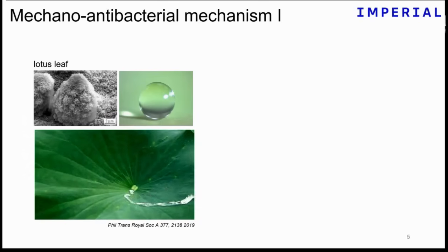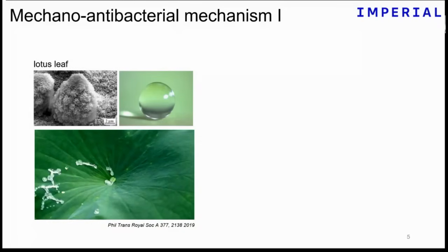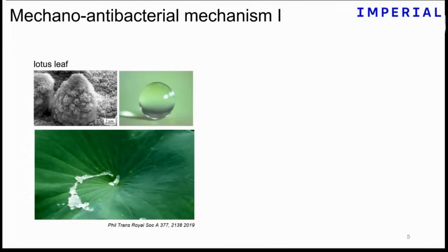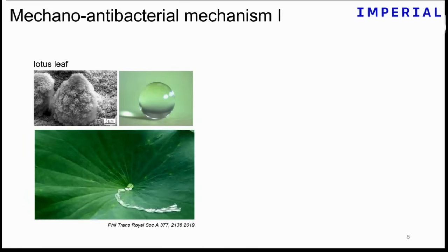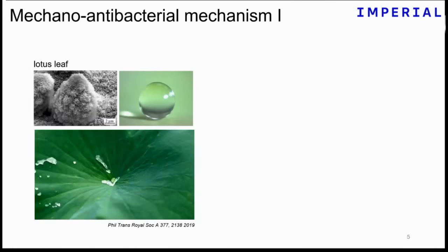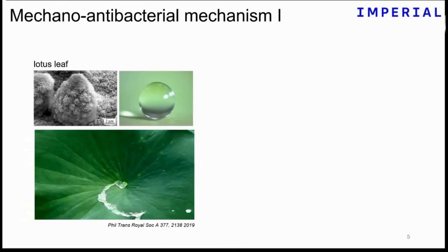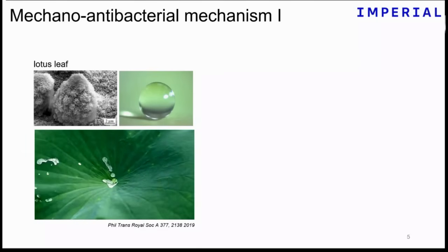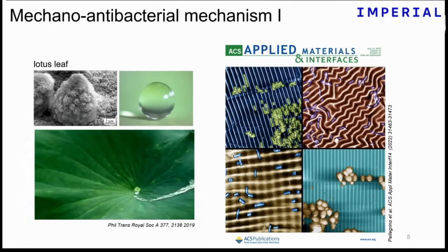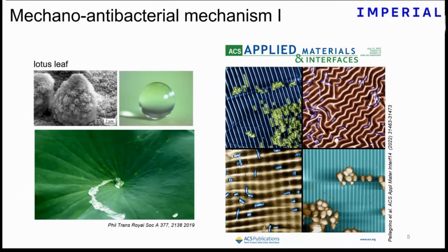Nature, of course, does that. In the first stage, you can see surfaces here, for example a lotus leaf, that has incredible superhydrophobic properties. They are known to come from their topography. The topography is generally multi-scale: something at the micro scale and then at the nanoscale. You can see that the contact angle for droplets is huge, so droplets will naturally roll right off. And sure enough, we can try to replicate some of those topographies in the lab. This is work from one of my PhD students.